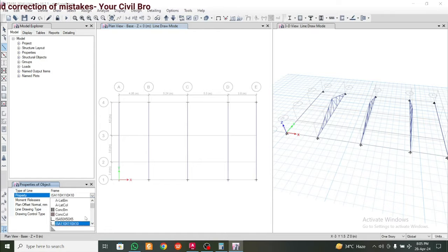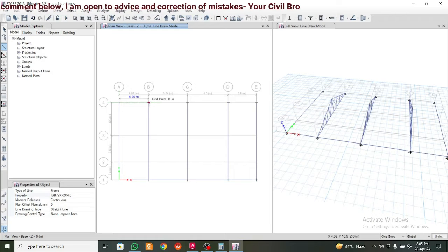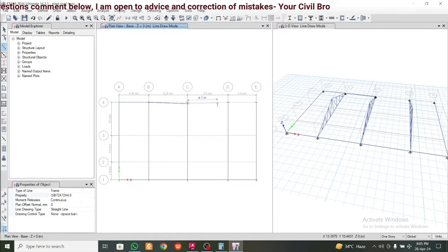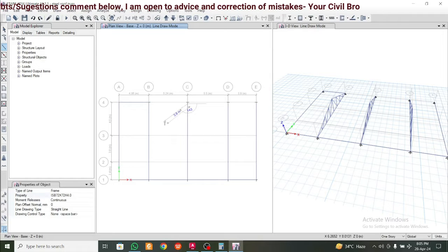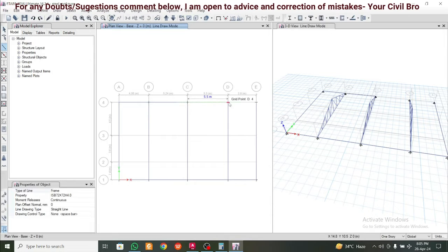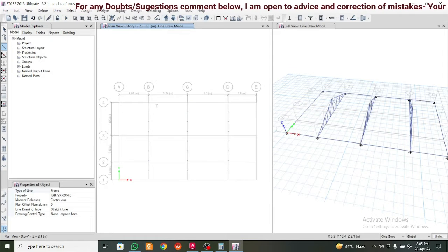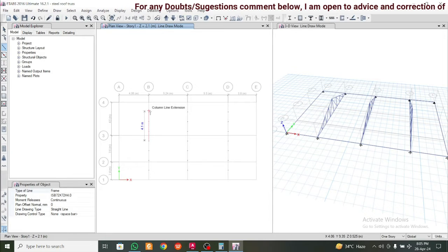So purlins will be in this property, the simple rectangular hollow box. So I like working on the plan in the purlins here. There are also other ways. Right click. Oh, I messed up. Ctrl plus Z. Right click to escape from the command. Just go above, and here now you have these joints readily available. So from this joint to this joint.